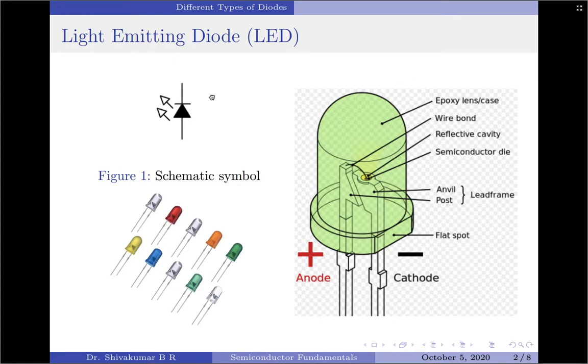In a lab, it is easy to determine the approximate forward voltage of a given diode by connecting it in series with a voltage source and current limiting resistor. The supply is increased until the desired brightness is achieved, and then the diode drop can be measured with the help of a digital multimeter.